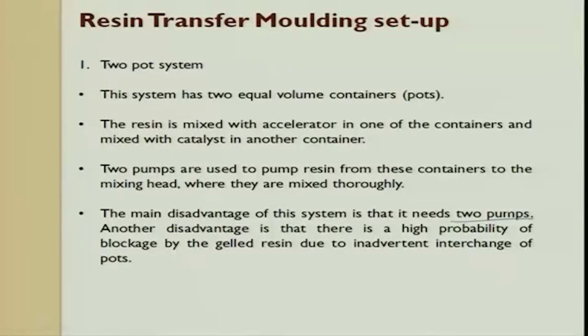So, the main disadvantage is it has two pumps and there is a high probability of blockage. Why? Because when we try to mix catalyst, hardener, accelerator, all those things, immediately the reaction starts, the gelation of the resin starts, and it might block. The moment it blocks, you have to clean the complete pipe.